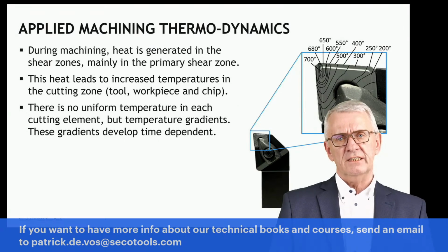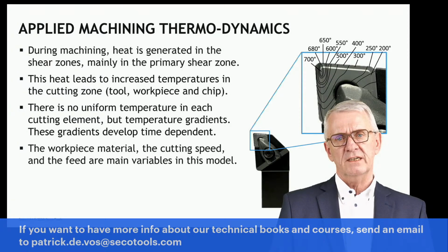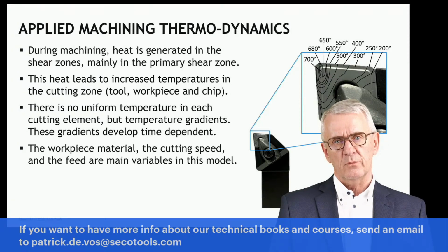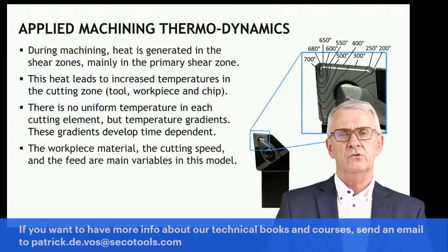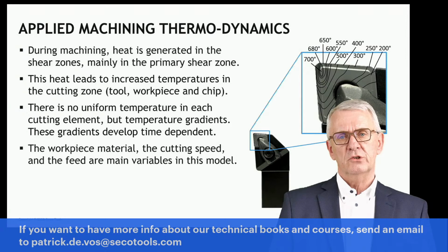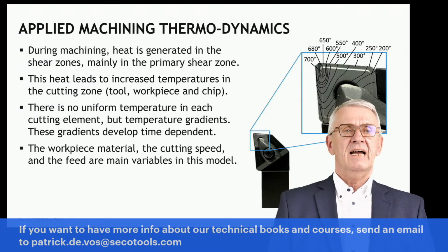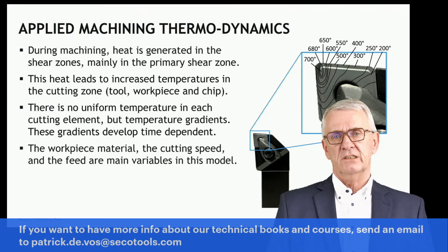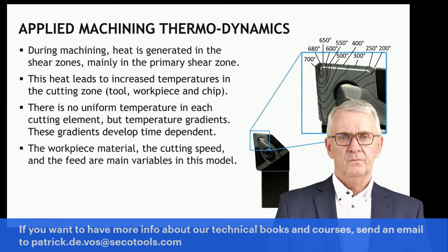Now, in traditional machining, it's not the maximum temperature that is potentially problematic. It's the gradient we have to worry about, because the temperature gradient leads to thermal stresses that could potentially lead to thermal cracks. Thermal cracks would lead to premature breakage of cutting edges and would limit the tool life, and all the other risks that come with a broken tool, an unexpected breaking tool.